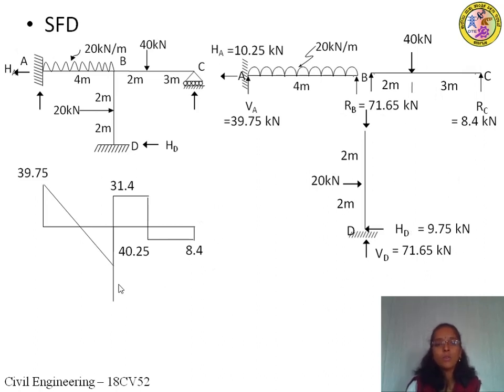Okay, so the positive shear forces are drawn to the right side of the vertical member, and negative shear forces are drawn to the left side of the vertical member. Okay, so how to consider the given forces are positive or negative. Whereas in the horizontal member we have a sign convention of upward forces as positive and downward forces as negative,